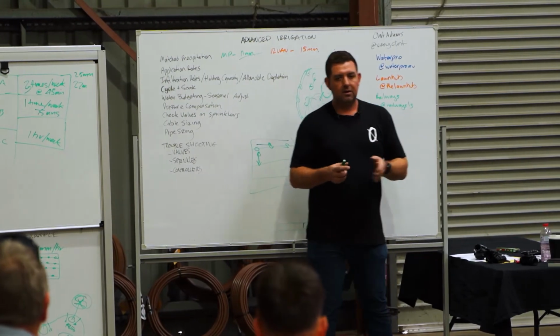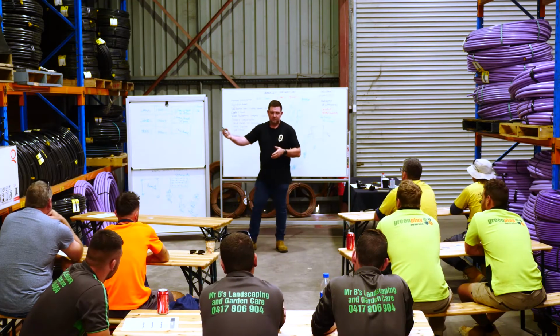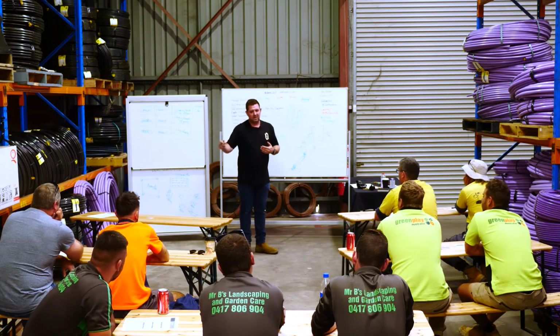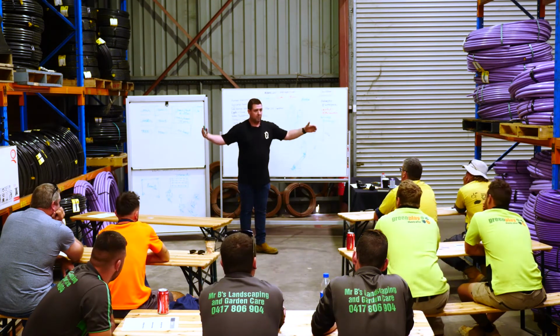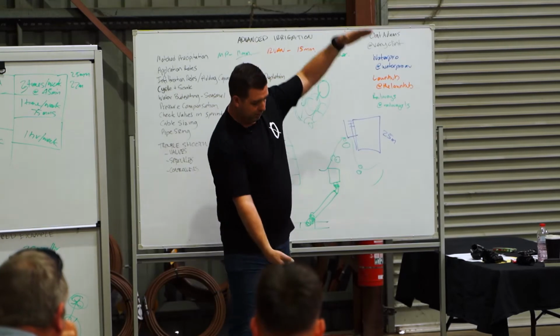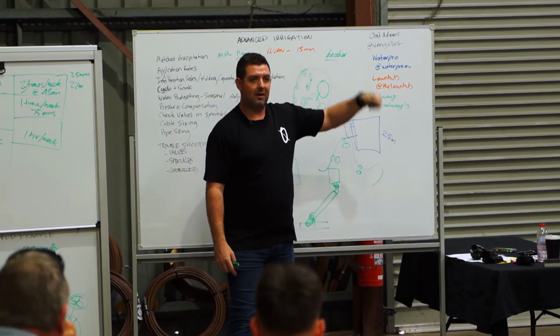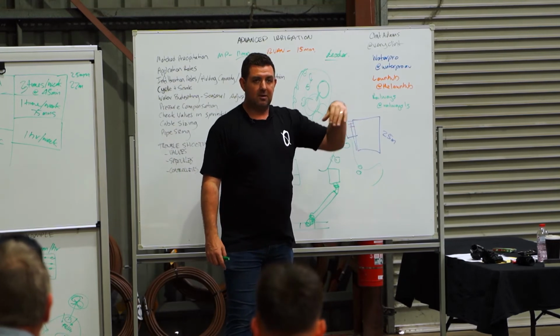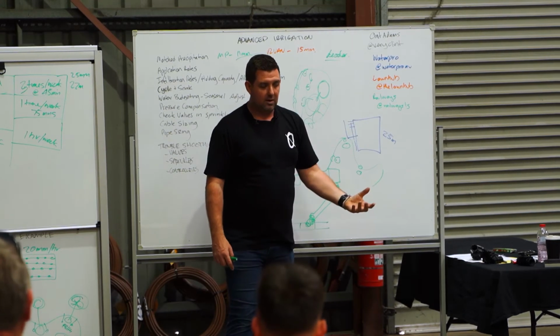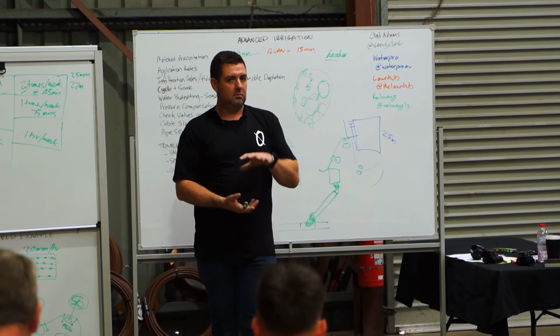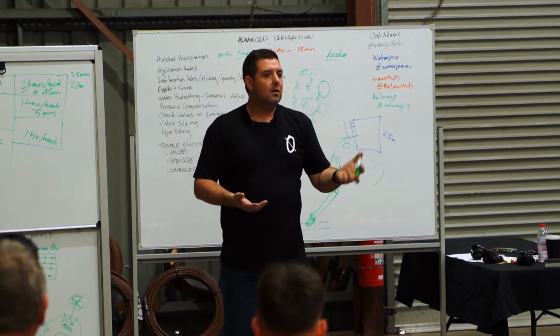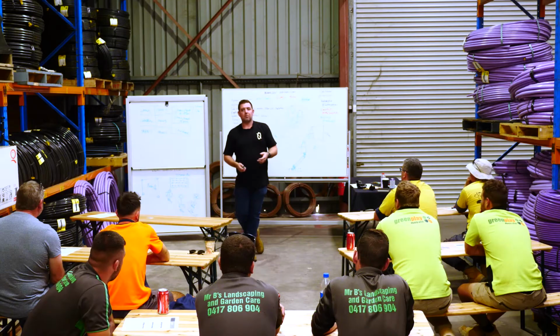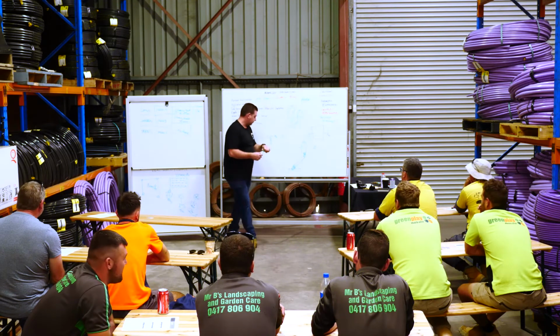And this is in manufacturer's specifications: every certain distance, and I think it's at every end and every corner, and then say every 500 meters or a kilometer, they put a brass rod that's probably 1.5 meters long, they smack that into the ground, and they connect it to the system, so that when that system gets hit by lightning, it sends that through into the ground and grounds the system and doesn't blow up the decoder. So handy to know. You're probably never going to come across it, but I figured while we're here, we'll talk about it.